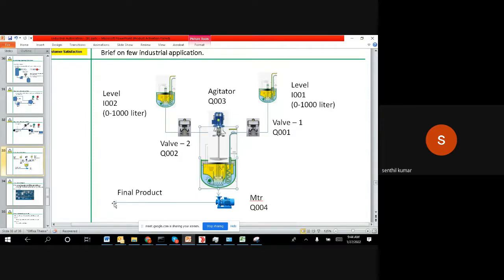Like they put in the centrifuge. The centrifuge will run at maybe 1,500 RPM. While it is running, when you are putting in the liquid, the semi-liquid material, all the water content will go out. Only the powder stays there in the centrifuge, and then they will take that powder out, and fill it into small tubes, or form it into different shapes, and then they finally close it with the aluminum sheet and sell it as a medicine.